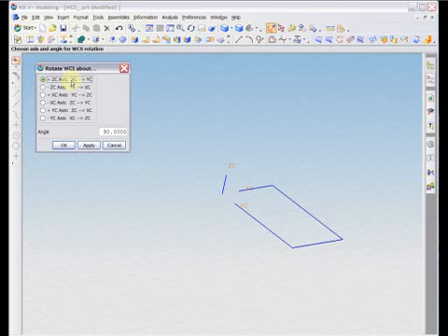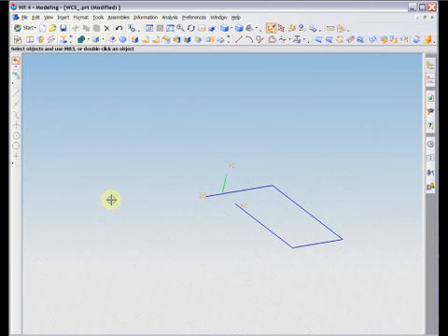For example, at the positive ZC rotation, the axis will rotate from XC to YC. This means that rotation around the z-axis will cause the XC axis to rotate towards YC. For our current model, we will rotate the coordinate orientation 90 degrees about the positive XC axis. Then we will simply draw 3 lines as displayed.